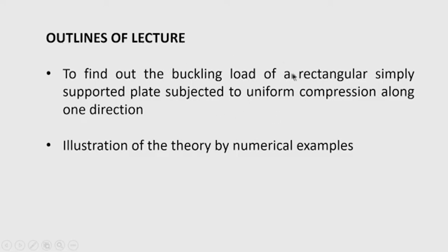Although the illustration is done with a uniform compression, the general formulation that I have derived in the earlier class can be used to solve a problem of rectangular plate with biaxial compression as well as the shear loading also, membrane shear loading.